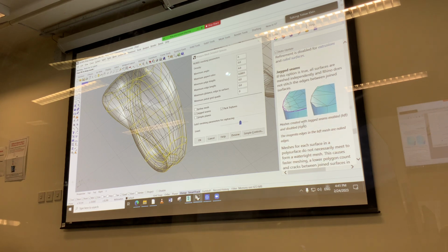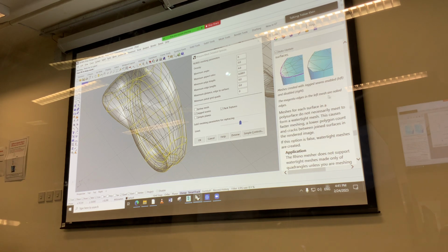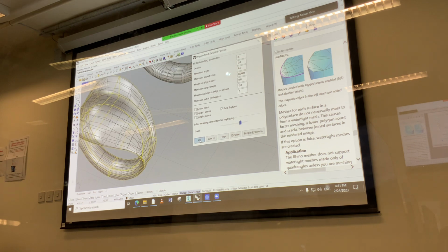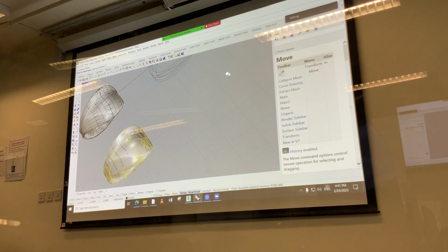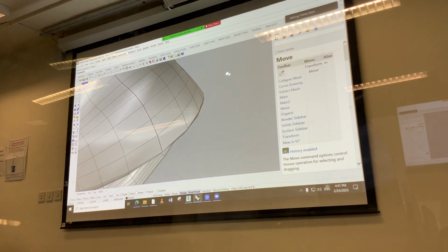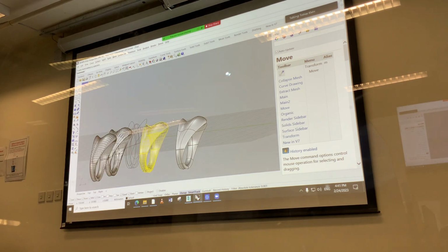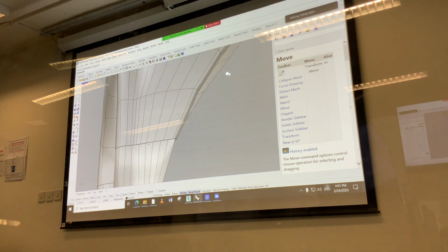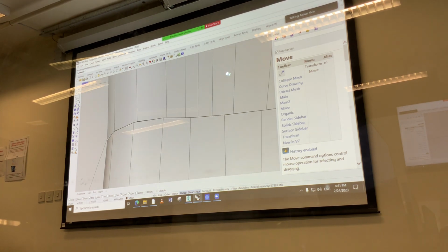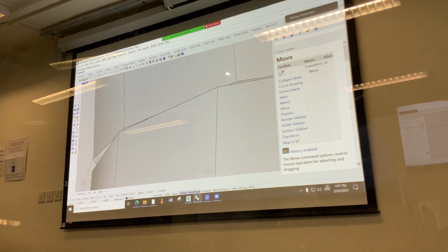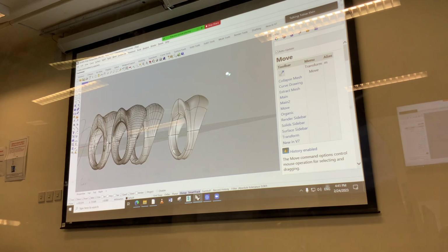Instead, we've got a mesh created with jagged seams on the left and disabled on the right. Magenta edges on the left are naked edges, and that's obviously a big problem. So we are forcing it here to abandon the kind of stitching between it. So let's say okay to that and look at this mesh for a moment. So what do we get here? We get a very, very clean mesh. Now here gets the interesting bit. With the jagged seams, we basically get two meshes that don't match each other. And if we get that, we can't really print it or work with it.